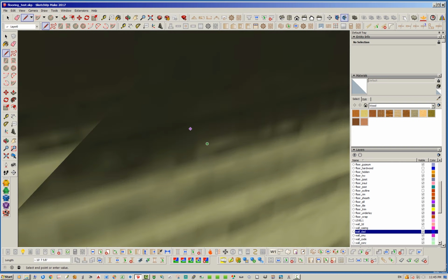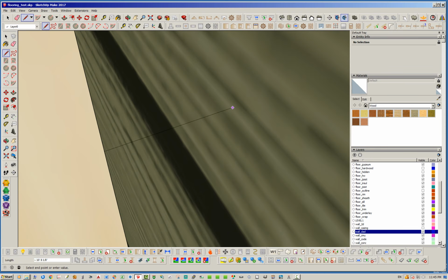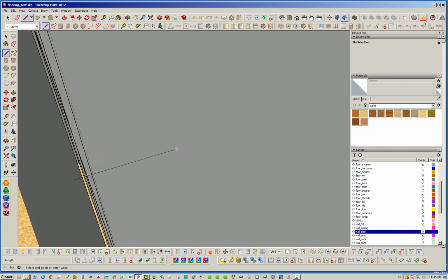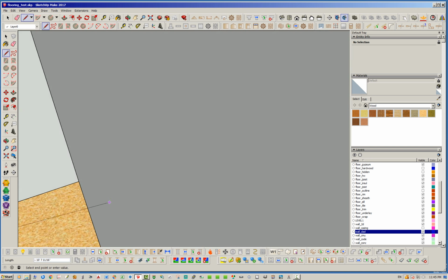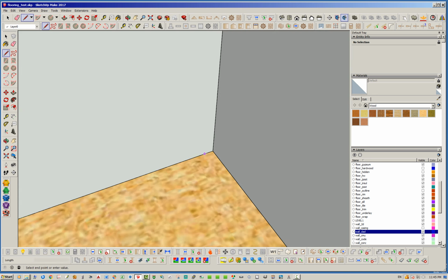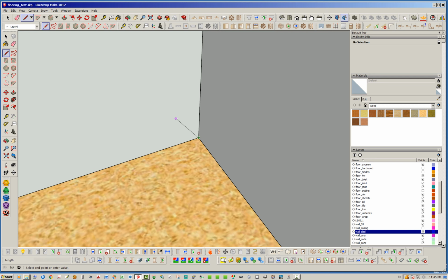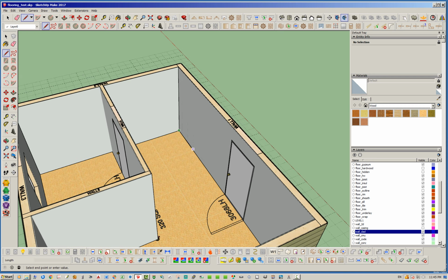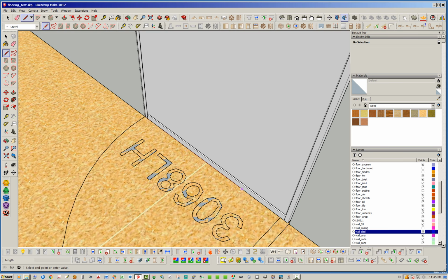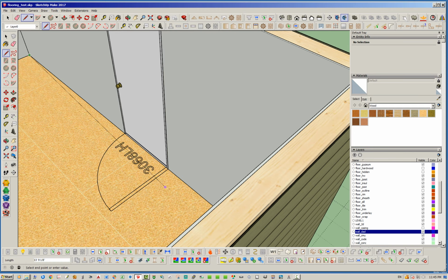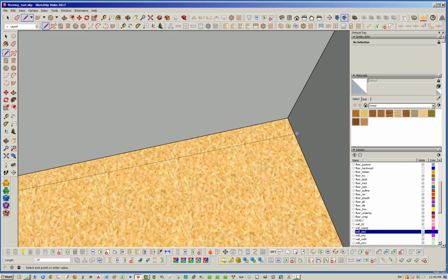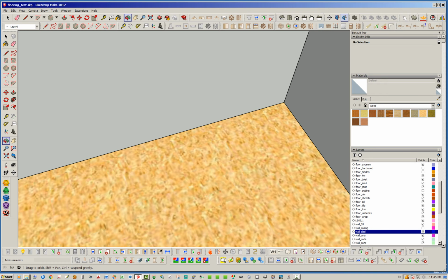Okay, and then we're just jumping around here. Oh, I've gone back into the wall. Don't want to do that. And then we just grab this corner over here. Okay, and we're almost there. Now, on this exterior door, typically you're going to have a threshold, and of course your carpet's not going to extend into that threshold or door opening, so we're just going to run right past it and terminate right here.